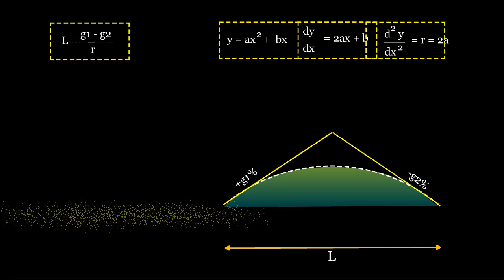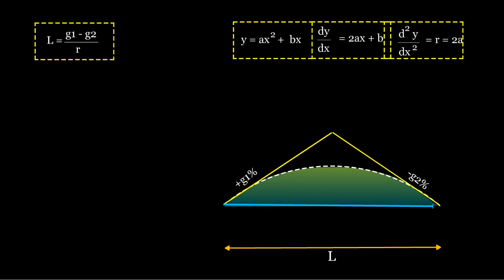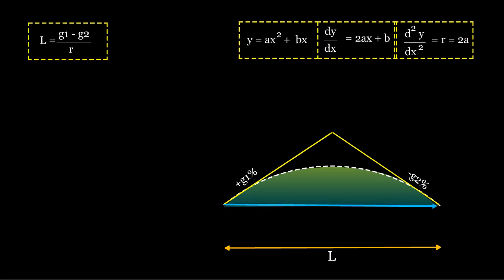In vertical curves, all distances along the curve are measured horizontally, while offsets from the tangent to the curve are measured vertically. This vertical distance, offset, between the tangent and the curve at any point is known as tangent correction, denoted as h. Let's define the setup.